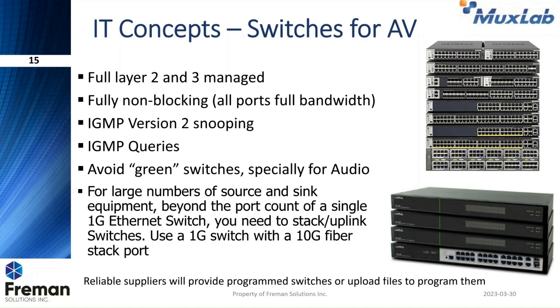And not all the switches are built so that the electronics on the switch, what is called the fabric of the switch, allows you to have that happening. And that's not a problem on the enterprise, because on the enterprise, signals have very low bandwidth. So even if all the ports are working at the same time, they never overload the switch. With AV, it would be very easy to overload the fabric of the switch unless it is non-blocking. And non-blocking means that all the ports can operate at the same time at full bandwidth. So for AV, always get non-blocking switches.